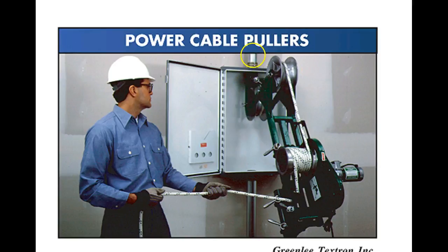So the rope that's got the cable attached to it actually comes down through here, goes through the sheave, comes down to the capstan. It's using a nylon rope, and as long as he holds tension on it and keeps pulling on this side, then it'll pull. But as soon as something goes wrong, he can just do what? He can let go of the tension of the rope, and then it starts sliding on the capstan, and it won't pull anymore.